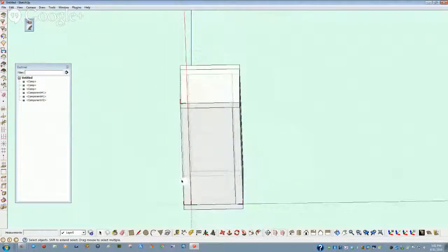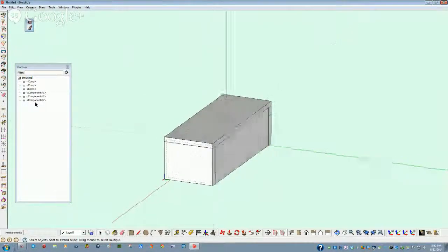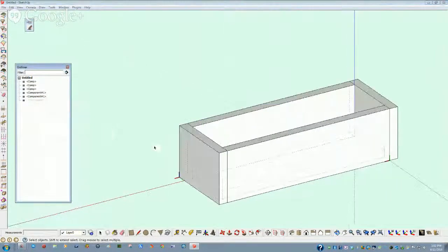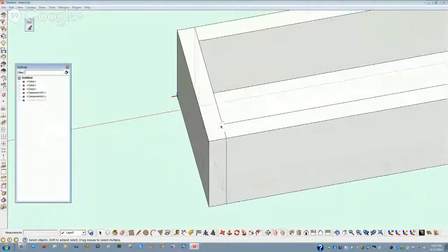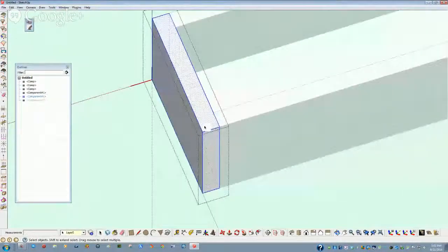You can see, like in every CAD program, once you get something done, you can find out you didn't really want it that way, or you're really, really happy with it. If we were to decide that no, we really don't want it to just be pin-nailed and glued as butt joints all over the place, we can hide the top. And we can miter these corners fairly quickly. I'll show you how to do that. Make this one active. Now I'll get into these 2 functions right here.